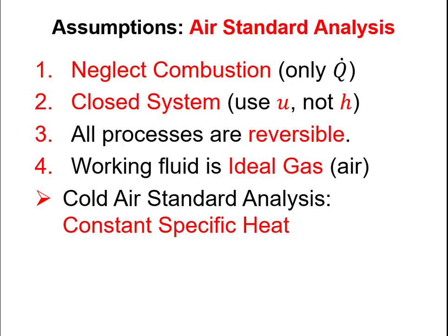So in our last episode, we talked about the Otto cycle and how we can use it to model internal combustion engines. To do that, we need to do what's called an air standard analysis. That involves a series of assumptions. We neglect combustion, so we treat the working fluid like there's no chemical process happening, no chemical reactions happening inside our working fluid.